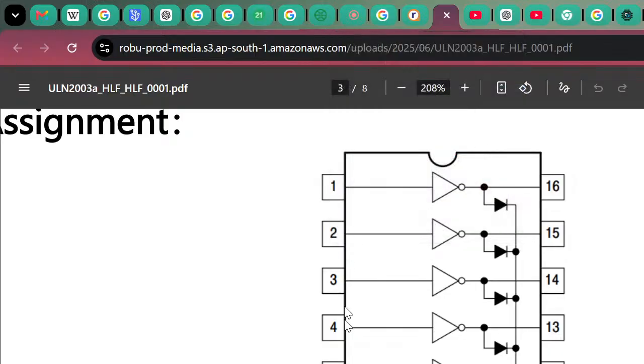So you can connect these 7 pins safely. No need to worry about anything, because internally you already have a current sink, Darlington transistors, and flyback diodes. Now these 7 pins can be connected to 7 GPIOs of an Arduino Uno. And with those pins you can control these 7 relays. The outputs are connected to a relay module.